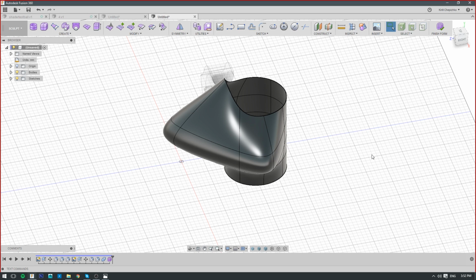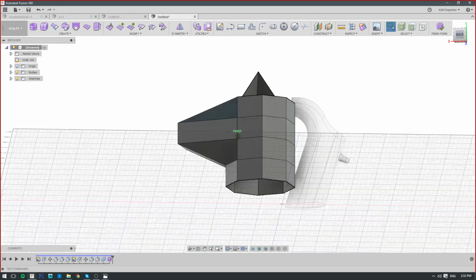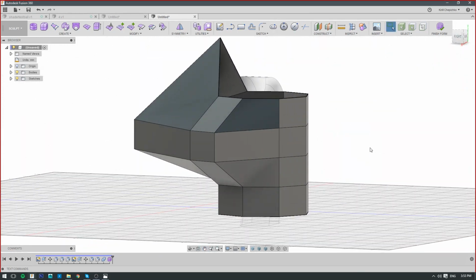A lot of times you'll just go into Maya, quickly do it, keep it quad, and you can import it back into Fusion, and then you can convert it. As long as you keep it in quads. You keep it very low poly count. So, for example, in Maya, it needs to look like this. And then Fusion will be able to convert it.